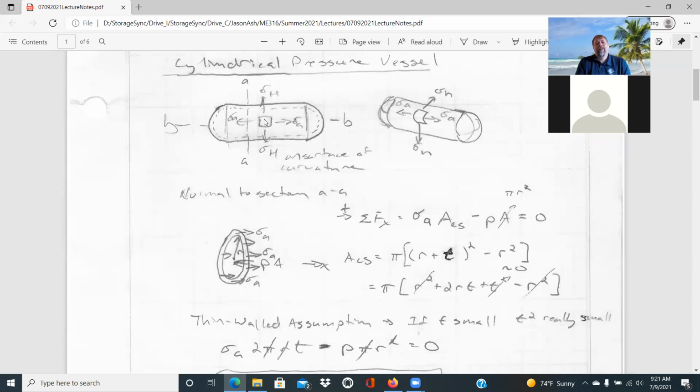And then another aspect of that is really trying to avoid that explosive nature of a pressure vessel failing. And so with those, there is a leak before break design for pressure vessels, where a crack is able to make it to the outer surface and release the contents of the gas before an explosive event occurs. And so that's something that I would always teach in machine design. I'm pretty sure Dr. Bruno covers that too.